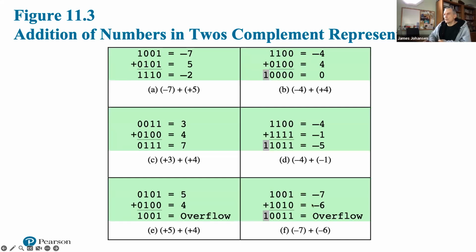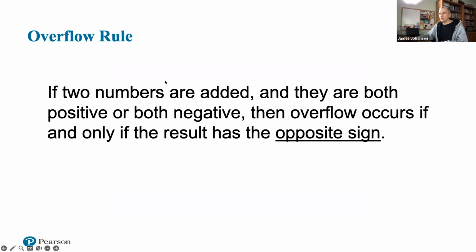So these are the kinds of things that we get a chance to be seeing, that we can start to get some greater insight into addition and subtraction. So basically, subtraction, with a slight caveat, is the same as addition, as we saw here. We just take the two's complement, and then we can just do an addition. So that actually is one of the things that can help us.